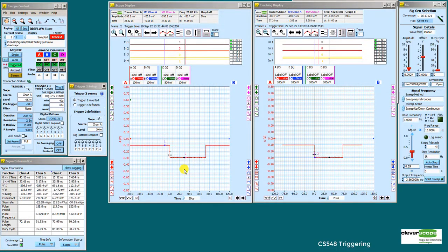We've been using trigger 1 inverted. Trigger 1 inverted actually means that trigger 2 is set up to be just the inverse of trigger 1, but we can do it ourselves. So if I go trigger 2 definition, I can see that it's triggering at the moment, and it'll actually keep triggering continuously because we have the trigger 2 level set to 200 millivolts up here, and so it never triggers with trigger 2, and so it always exceeds the 60 microseconds.